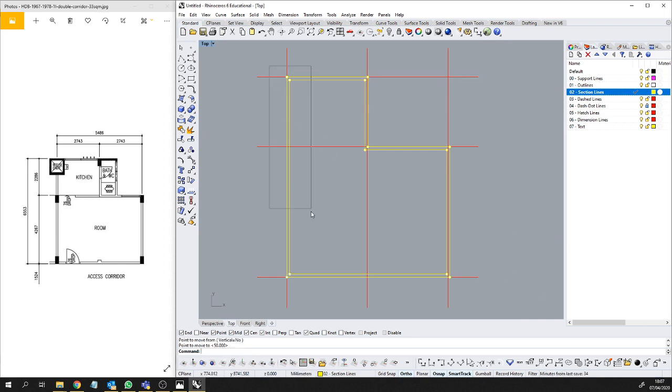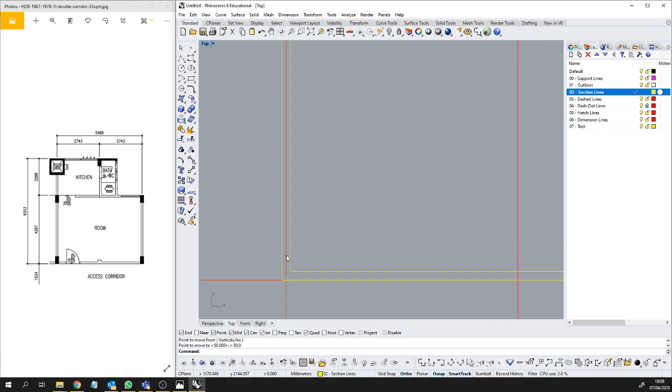Let's do that again. Something went wrong. We click both lines. We activate the 4 points. Then we type move. We click anywhere. Then we type in reference minus 50,0. And then again, we see that the middle of our grid lines is to the middle of our wall.